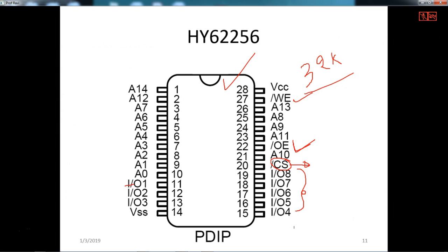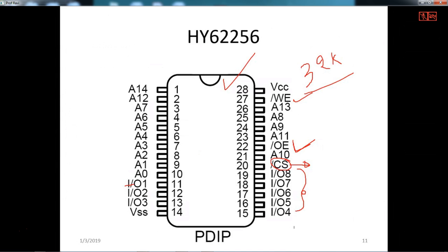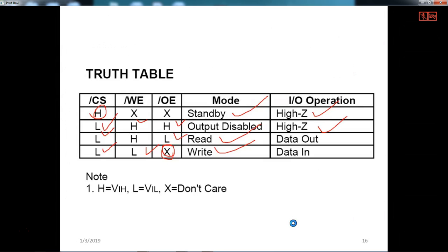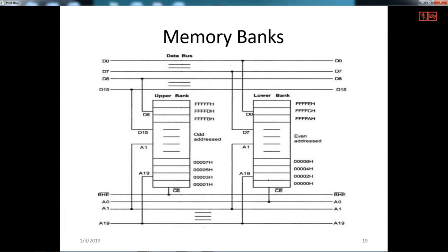This is what is there in your Electro Systems 8086 kit. So that's why I am showing it. So here, the moment you want to interface this, then this is what we are trying to see: RAM A0 to A11, and then you have output enable, write enable, and here you have chip select, and then here you have the data lines, and then here you have the address lines. And now coming to the DRAM interfacing, when you try to see,